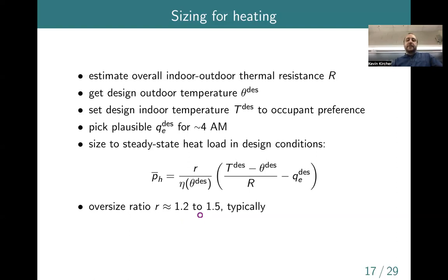But anyway, if you look at the recommendations from a group like ASHRAE or AHRI, the American Heating and Refrigeration Institute, for a number of reasons, they recommend actually not oversizing crazily. So you want to be pretty close, actually, to the design load.